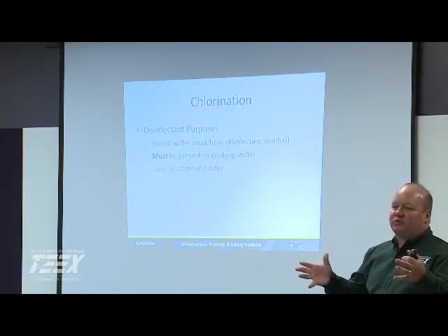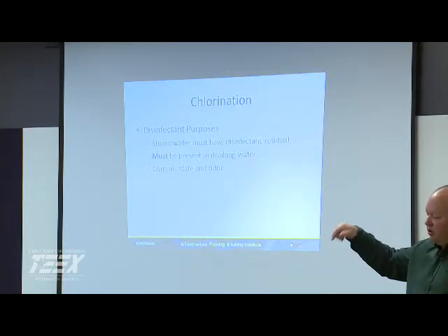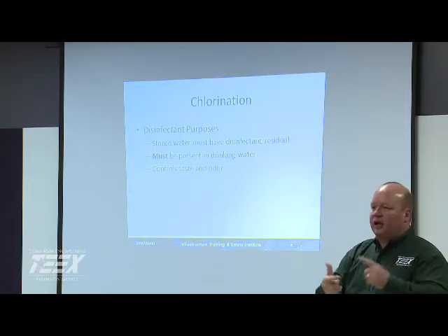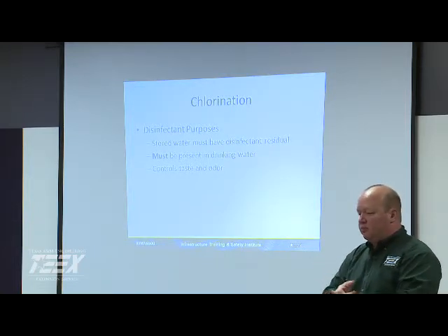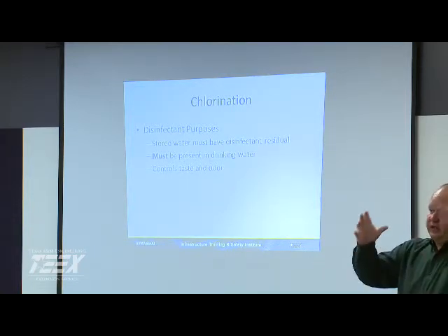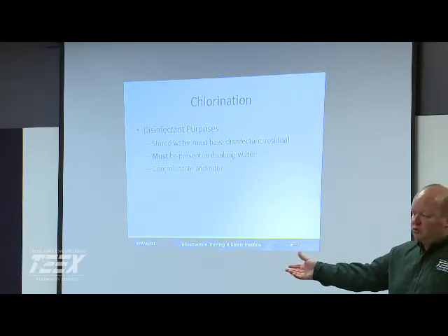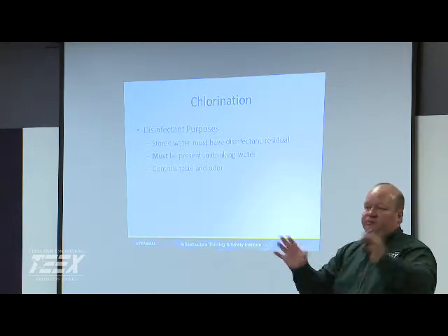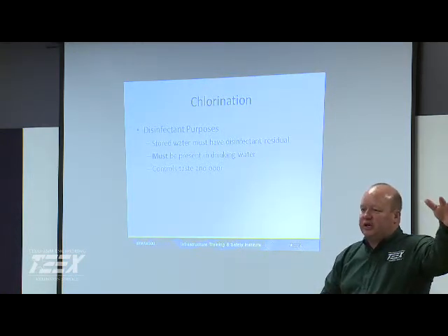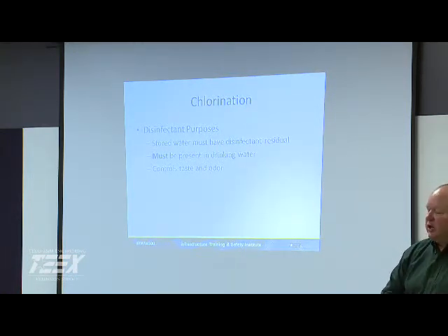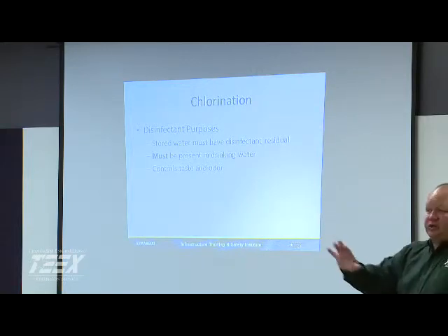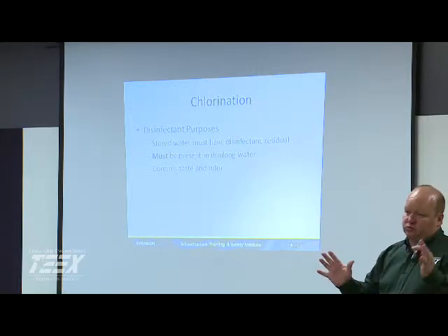At that ASR facility, when they did their initial pilot projects, they had real high iron and real high manganese levels. So they brought in and had a silo full of potassium permanganate. Once they actually got the wells drilled and started bringing in the water, iron was easy enough to get out just by a cascade aeration, and there wasn't hardly any manganese, which was great.